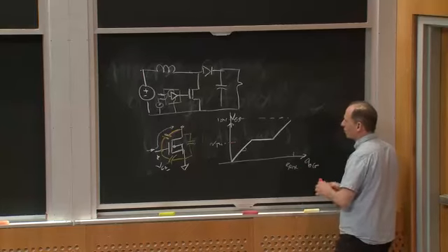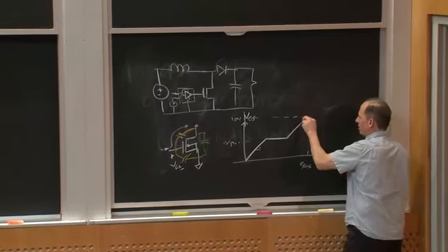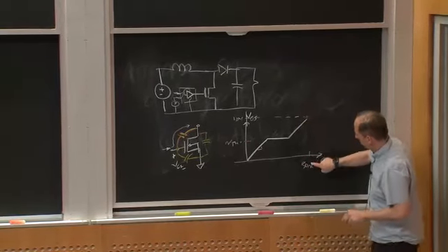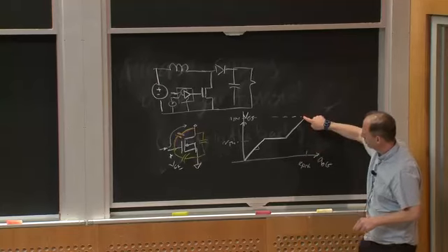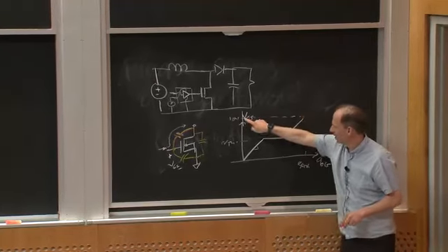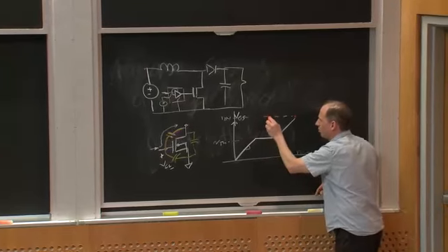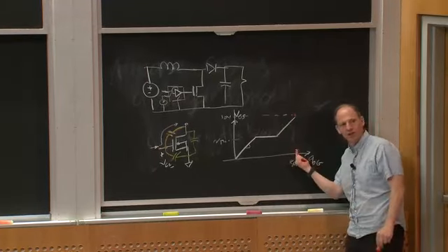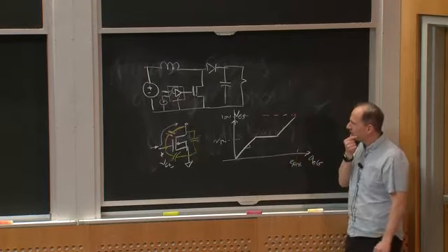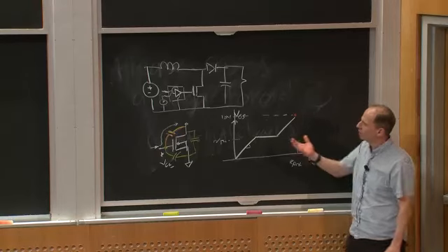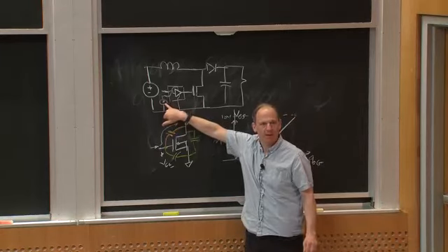What I care about is that I need to source this total charge to get to 10 volts. If I only paid attention to what this capacitance was, I wouldn't calculate the total charge I needed. And how much energy do I lose from this gate drive power supply?